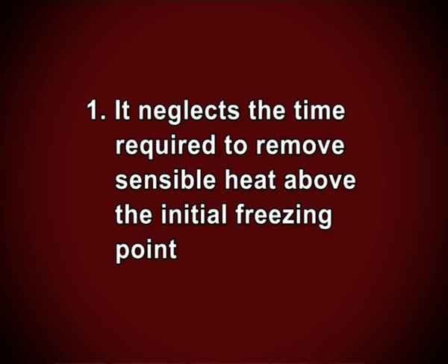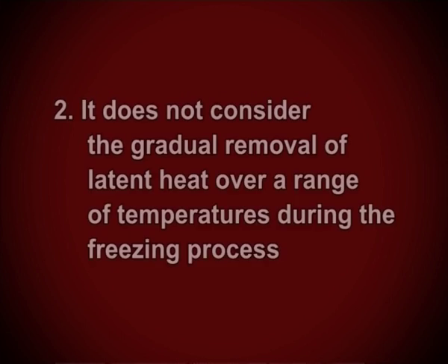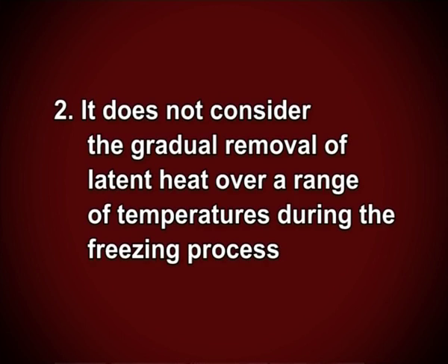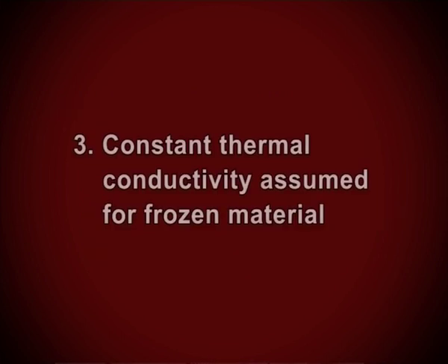1. It neglects the time required to remove sensible heat above the initial freezing point. 2. It does not consider the gradual removal of latent heat over a range of temperatures during the freezing process. 3. Constant thermal conductivity is assumed for frozen material. Despite these limitations, Planck's equation is the most popular method for predicting freezing time.